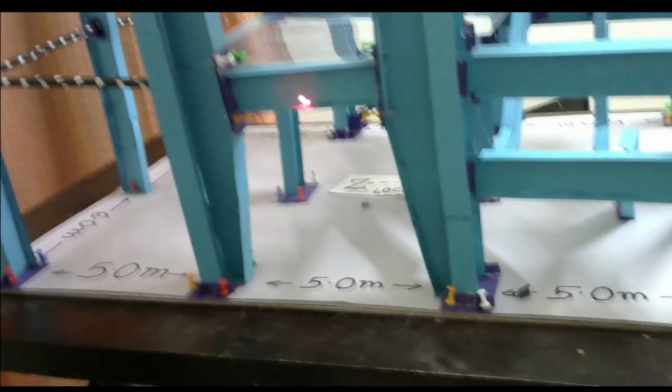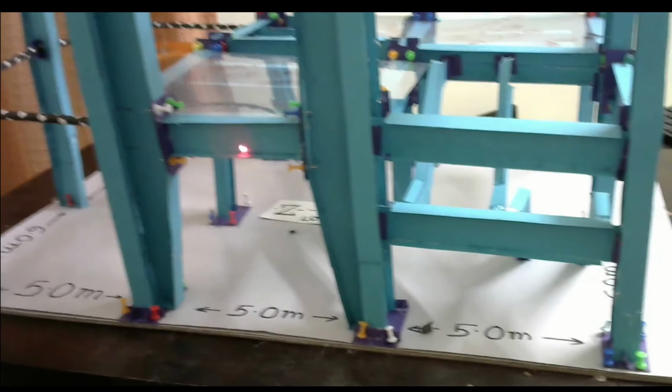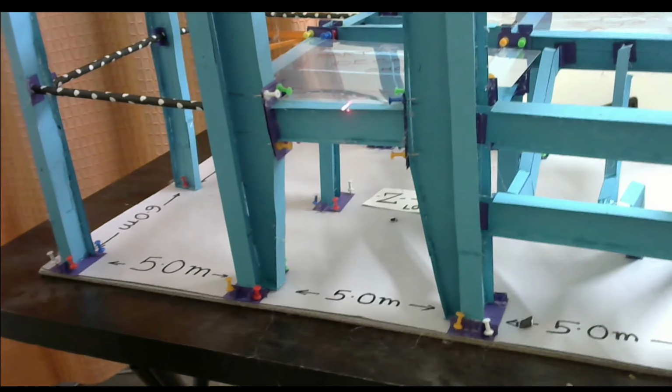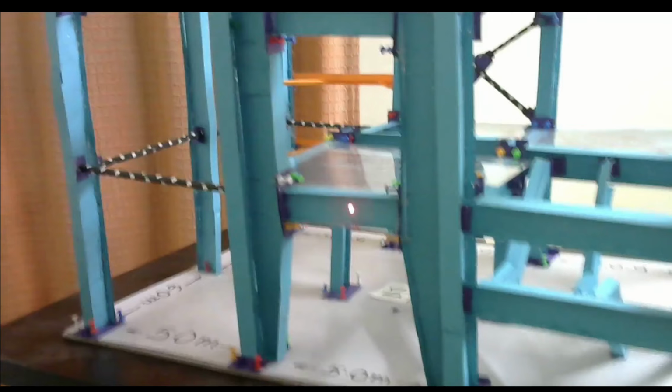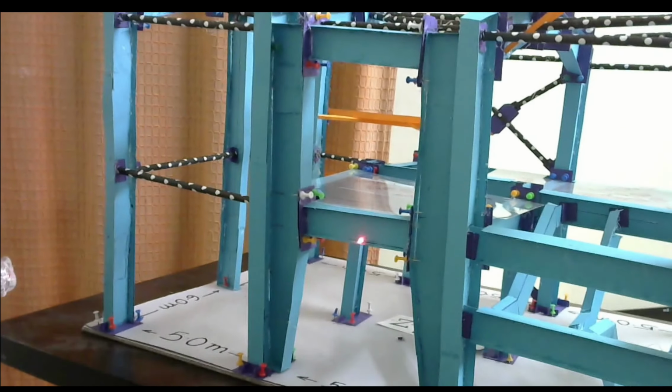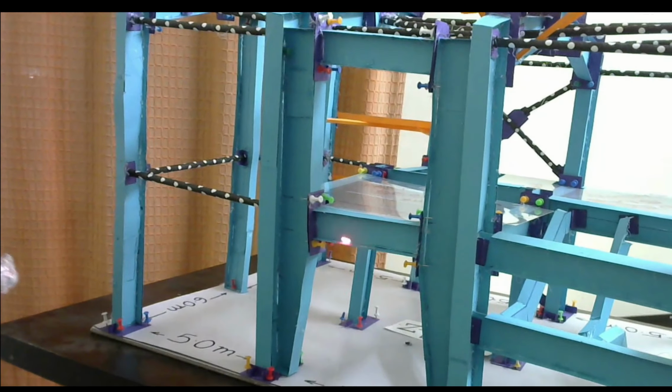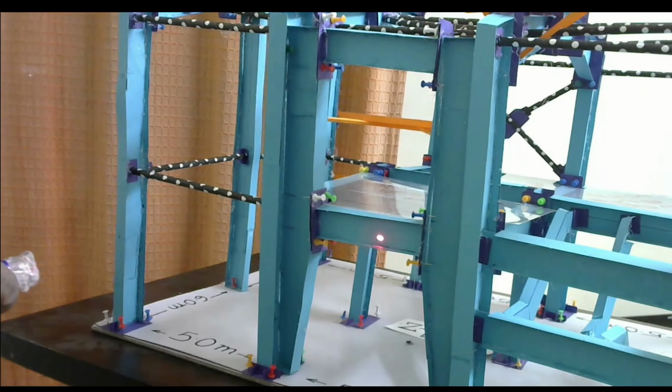This is the beam. Actually, British code allows the point of contact fracture to be taken as torsional restraint, but the American AISC code says exactly the opposite; it says that is the most vulnerable point. So we should take the whole length as LX, LY, LZ for this.